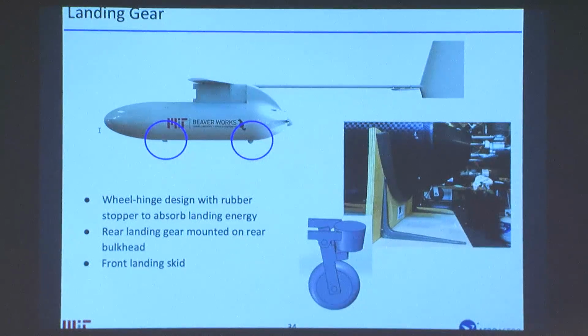One of the interesting things here is if you've been paying a lot of attention, you may have noticed that the prop diameter is larger than the fuselage. So if you look at the airplane from the back, the lowest thing you see is the propeller, which doesn't work so well for landing or takeoff. The way we get around that is that the car has a launch rack that provides clearance for the propeller. The airplane actually leaves to the back of the car. It backs up as it takes off because the car is going so fast.